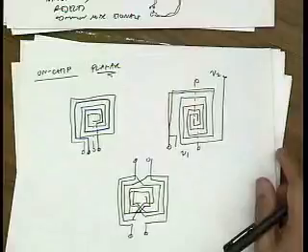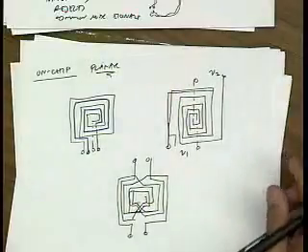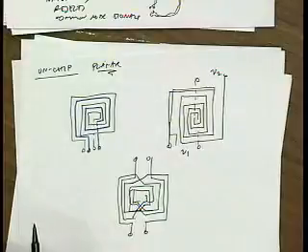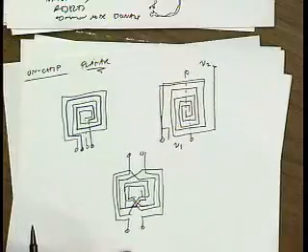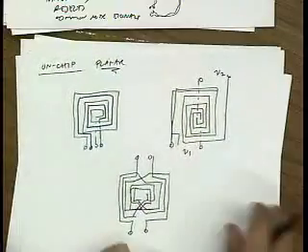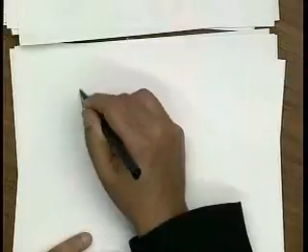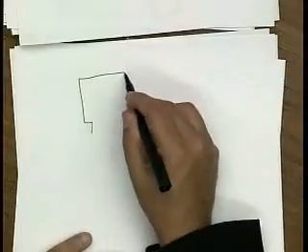Yes? So in the twisted pair example, and even here, how do you make a transformer with turns ratio not equal to 1 to 1? That's a good point. Generally, it's harder to do that. You can't do very large ratios. What you do is you put turns in parallel. So let me show you how you would do that on chip, and then you'll get an idea. So let me say